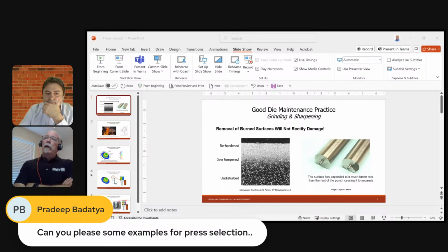Another scenario, especially if they're short feeds. Again, I present this in the die design seminar in April. For a high-speed application, you have a feed shelf where your material is, an extension to the die, with a lower plate and upper plate, and the material travels through the plate into the die area. We've milled out the top portion of that plate and positioned a sensor over top of it.